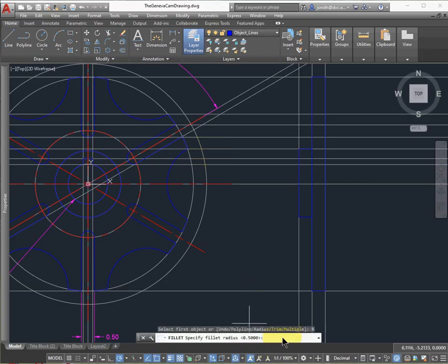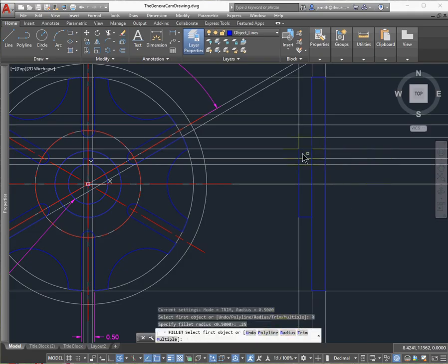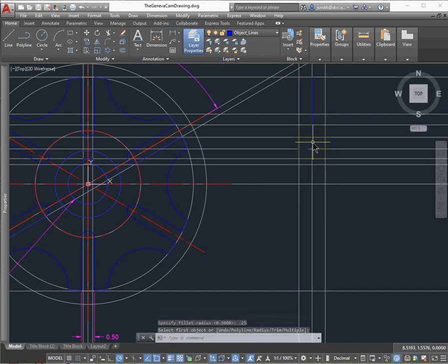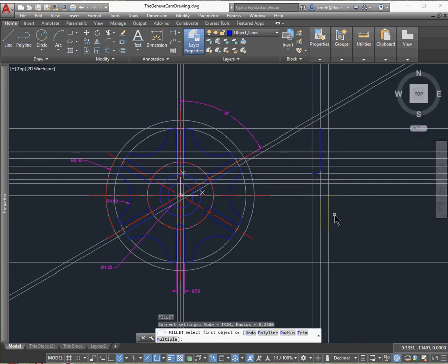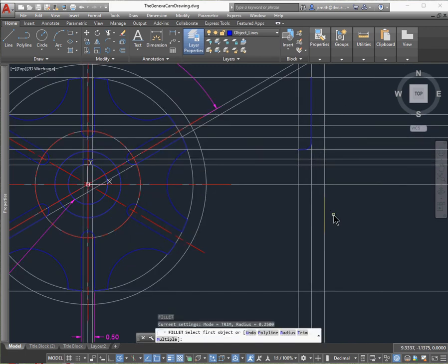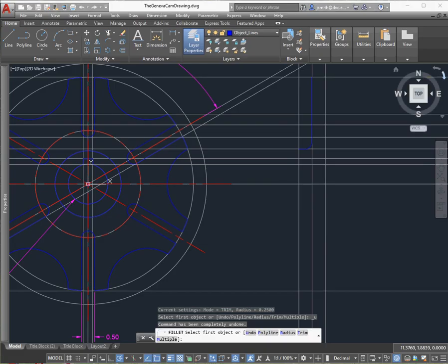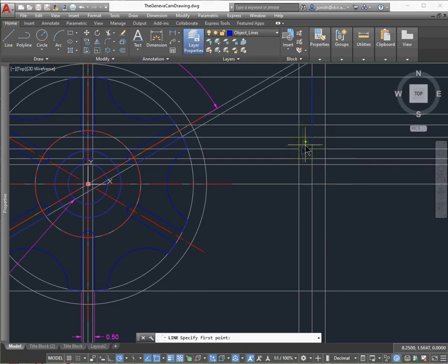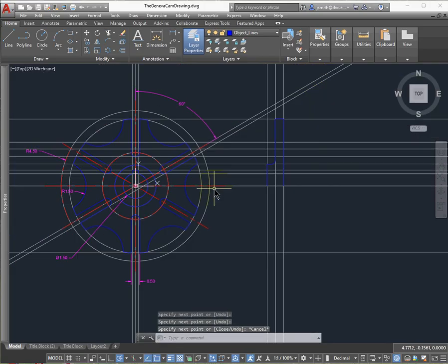You basically select the left line and the right line here, and there it builds. Now you notice all the other lines disappear, right? So I'll just very easily build that back in here, not a big deal, because I have those construction lines, and I'm just going to make half of this. And then I'll just mirror it. Escape, and the outside is consistent, so I'll go ahead and type in mirror.